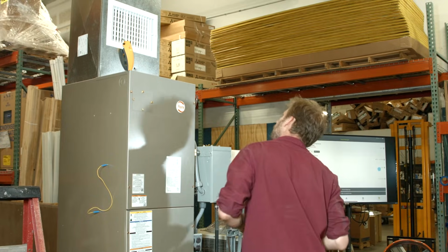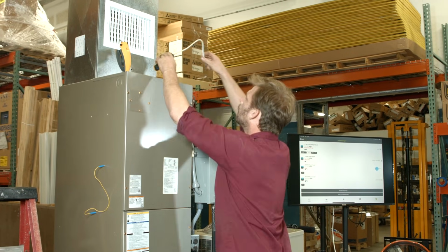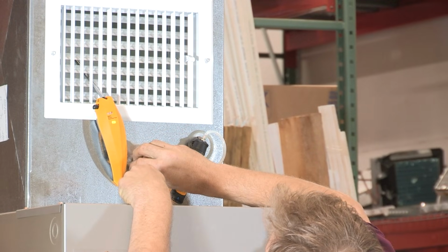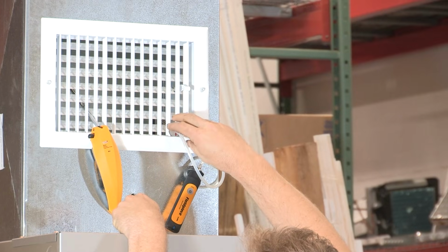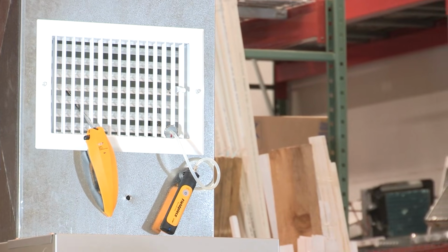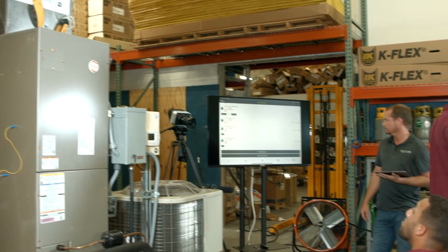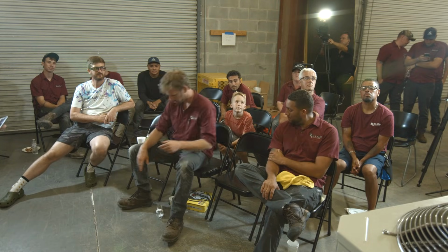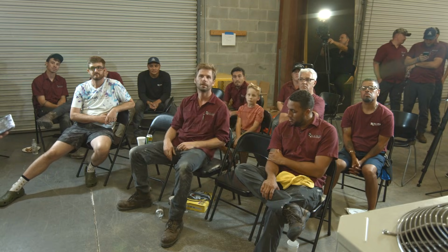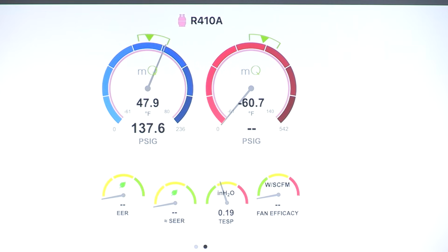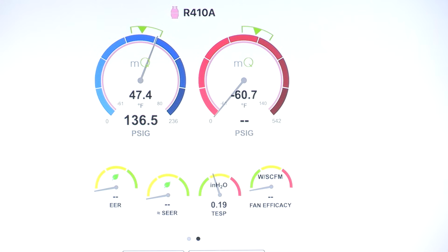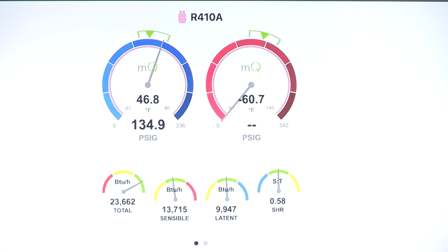It's super cold. Our return static is next to nothing. Put a piece of cardboard in there. There's that other hole sitting right there that's exactly for that purpose. Yeah, but it's not good enough. Oh, okay. It's too low, and it's not in the flow of the forward. All right, so our return and supply are very, very low. Total external static is 0.2. Perfect.